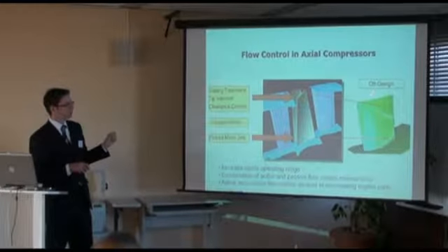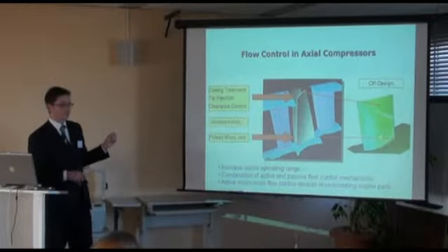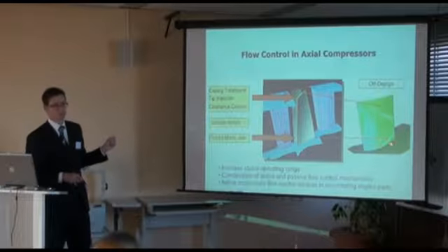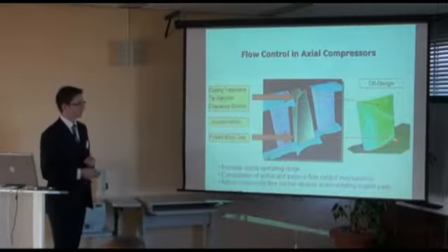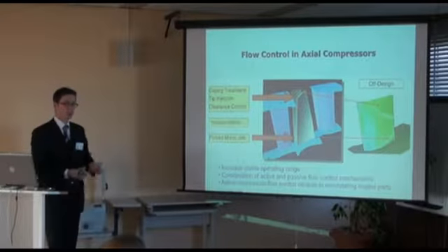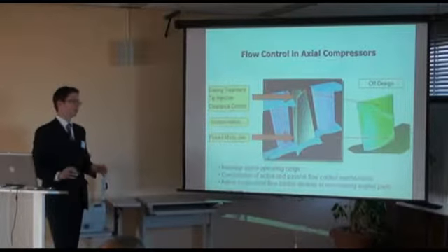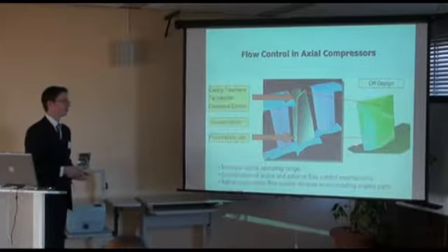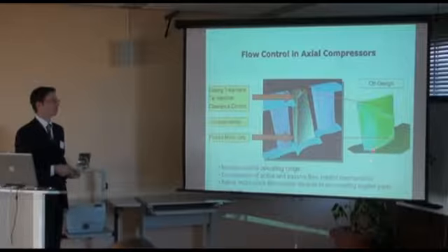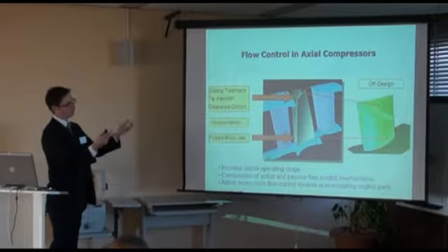But there's also a complete flow field over the airfoil, and there are other regions which are important if you want to enhance surge margin, like the hub, for example, where you've got horseshoe vortices, as we call them, rolling vortices from the hub to the trailing edge.